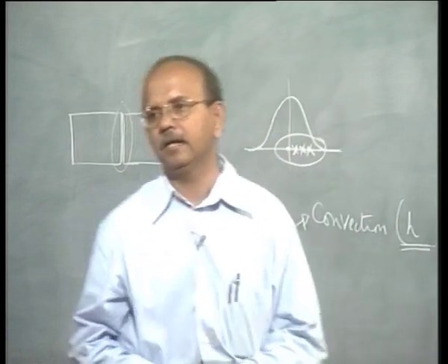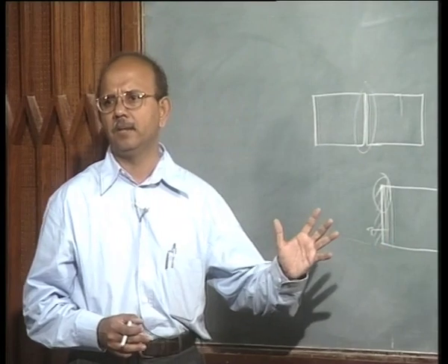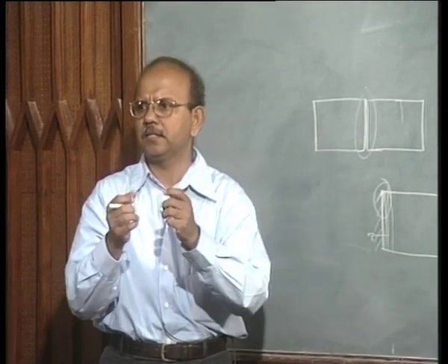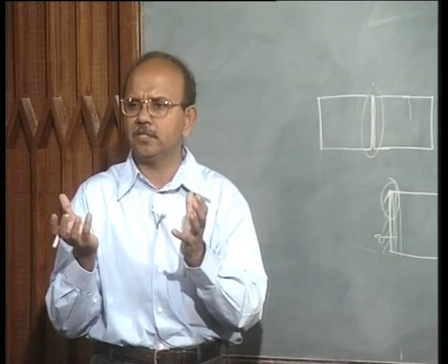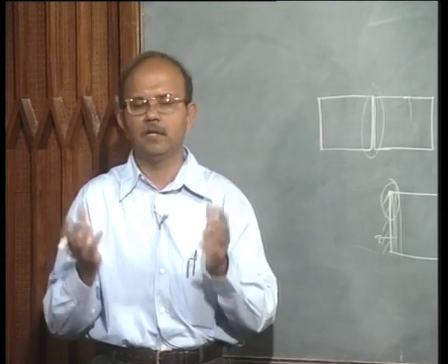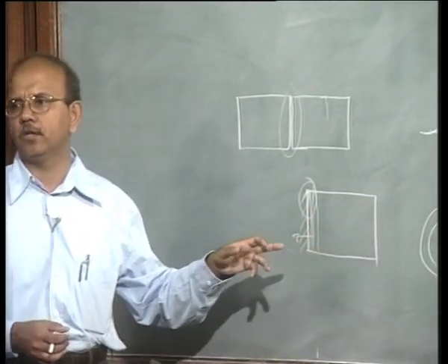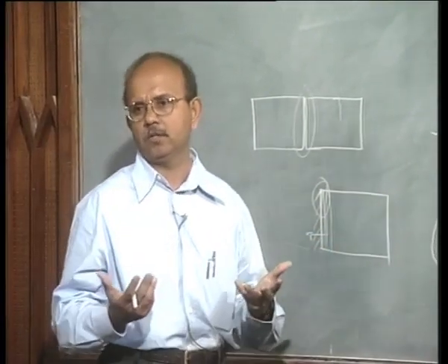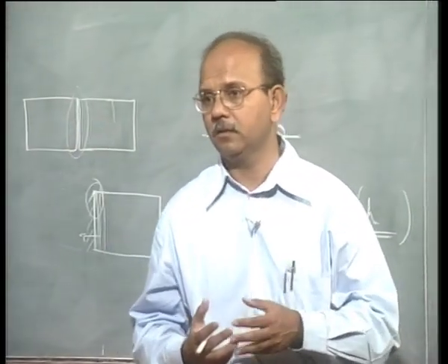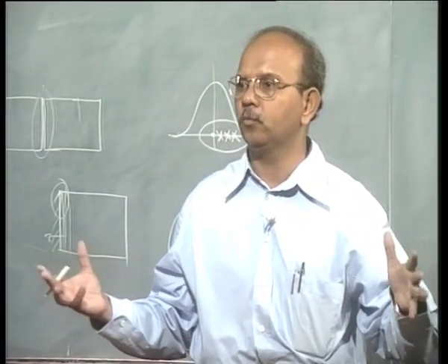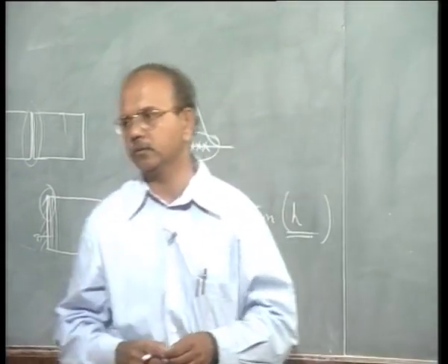Let us say that I am holding it, for example, I may not hold it, but in this case I might have held the pipe at certain position, hold it very firmly, because for welding there may be some fixtures, assume that there are fixtures here. So, at that fixture position, you may hold the nodes, but it depends, you may not even have a fixture, because large pipes when you weld it you may not have a fixture to it.